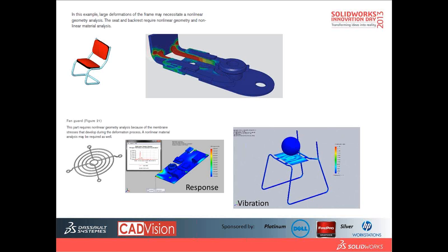When we plug something inside, the design of the shape of the snap fit is very important, right? Because it relates to the stress during the contact, and we need to know what the high stress area is and how to reduce it to avoid failure. For long-term usage, we're going to snap fit quite many times.